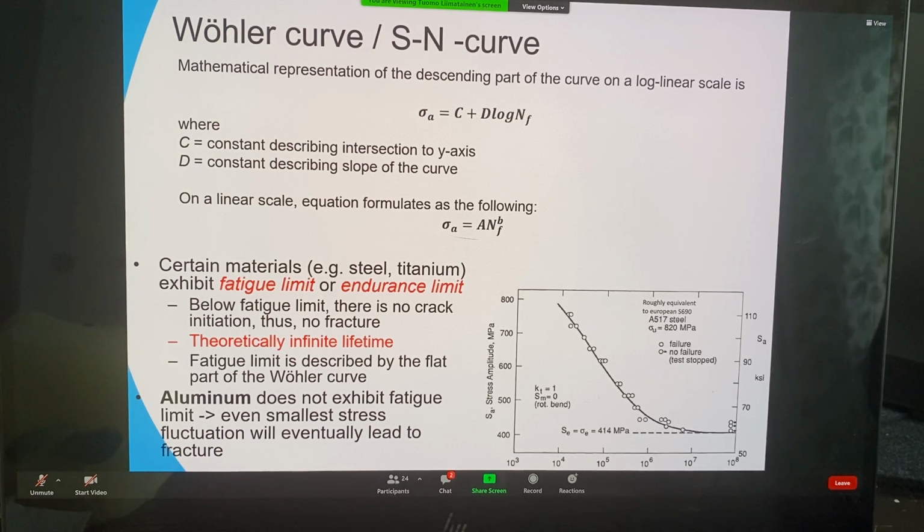That is a very good question, actually, and you are going a bit forward on that because later we can see an equation where we can combine effects of different stress variation levels. That's the so-called Palmgren-Miner rule, where we can see that if we have different levels of loadings, some of them are here in the sloping part of the Wöhler curve, some of them may be below the fatigue limit, and how to combine that effect and how to calculate that. There is an equation for that.